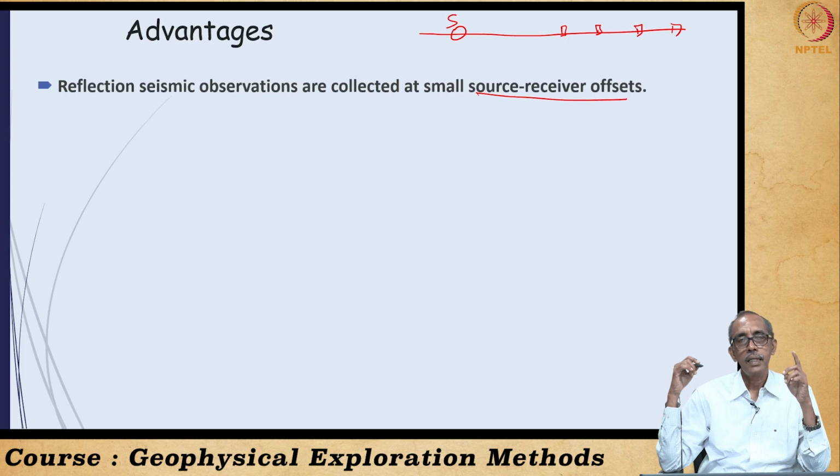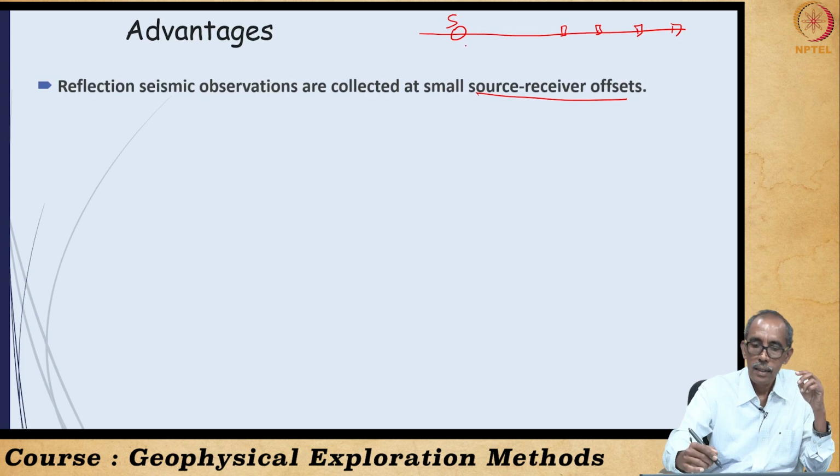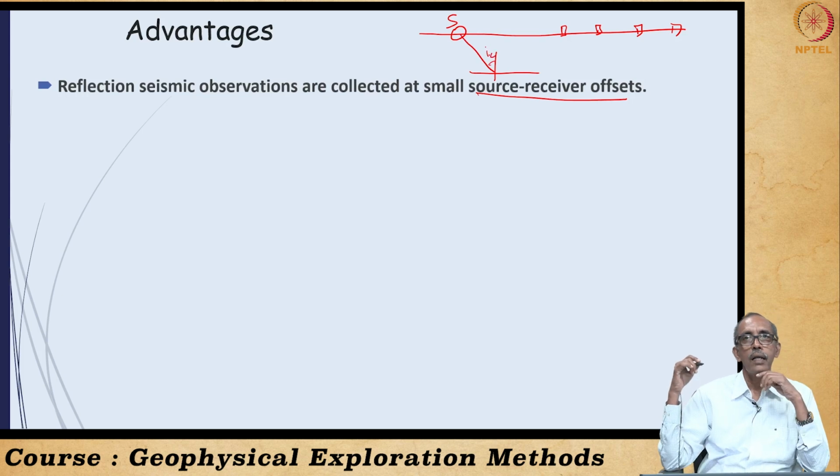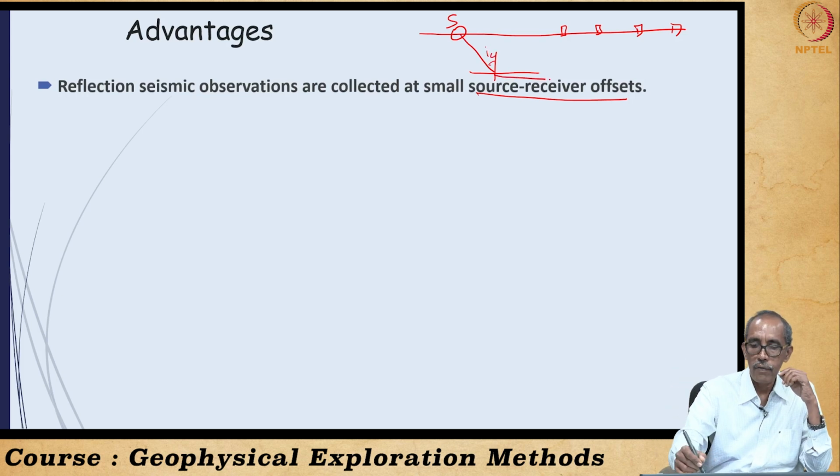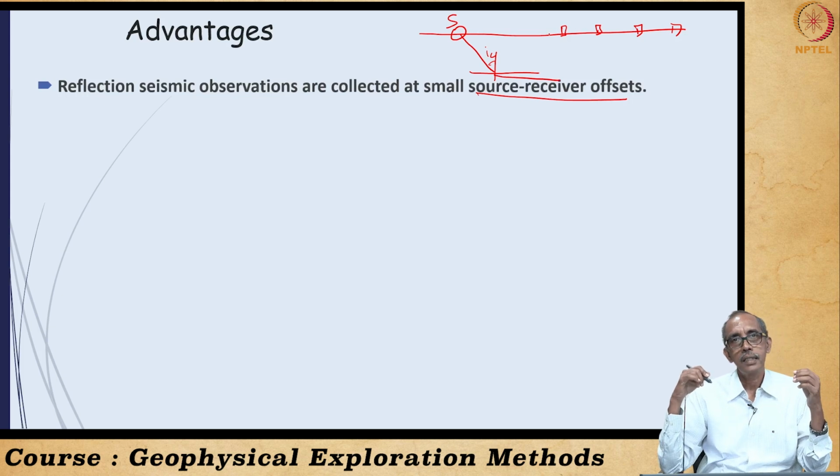And we had seen already, in order to receive a seismic refraction signal, the shock wave should meet the interface at the critical angle, only then it will get internally refracted. So, up to a certain distance on the surface, we will not get seismic refraction.